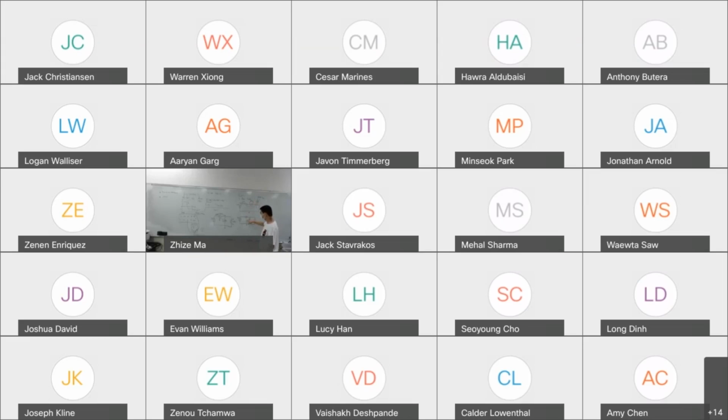For this configuration, it's a little bit different. It is one light bulb in series with two light bulbs that are in parallel with each other. This one is in series with these two, so the current will be different for each of them. These two will be similar, but they may not be totally the same, so you still need to measure them separately. Similarly, when you measure voltage, you put the meter in parallel like this. That's how you measure the voltage.